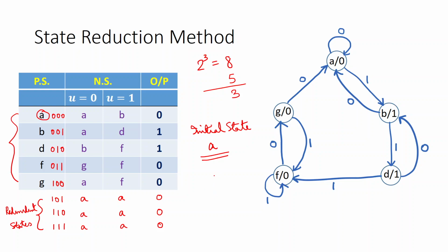The first step is of course to form the complete state table as you understand. So that has been covered in the previous lecture. We have solved different examples. So you have come to a state table. From that you have to do state reduction. After you have come to the state table, you see whether there is a possibility of state reduction. Then you get the reduced state table.